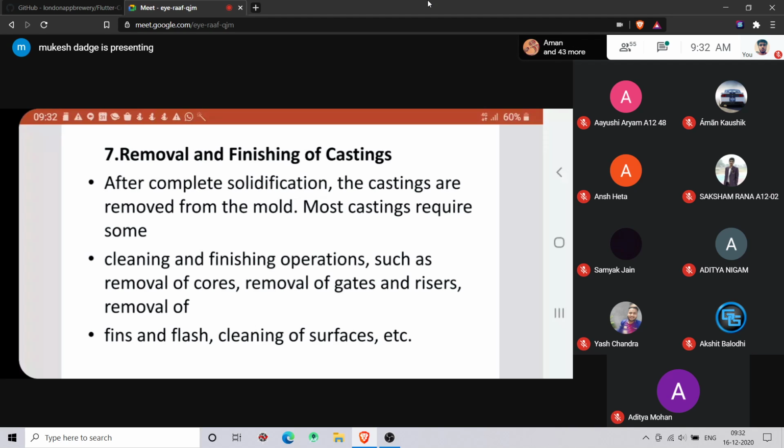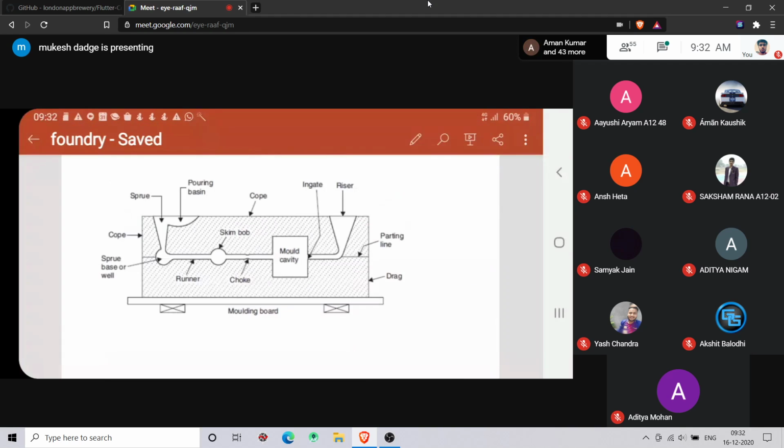So after that, one casting. I have shown you the piston in the last class, the piston cavities, cast product and finished product. After all the machining and removing the risers and runners, if you see, the mold cavity is only your final product. All other things are wastage. You remove that, you have to finish that mold cavity product, and you will get the final product.